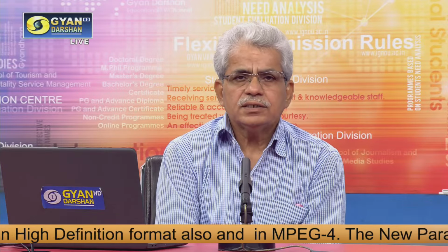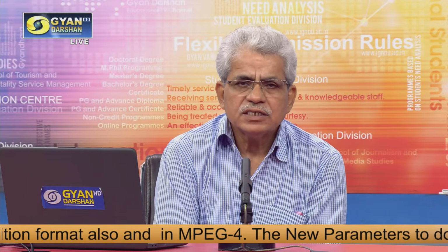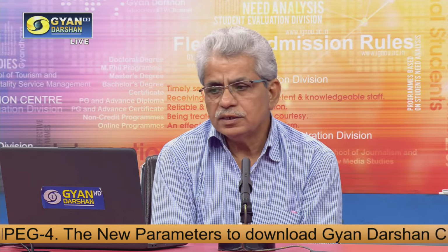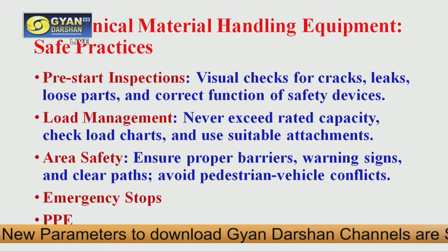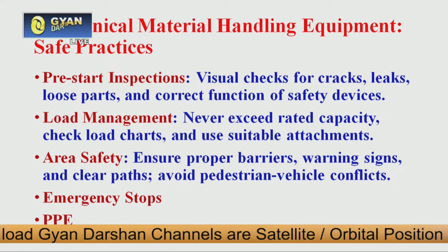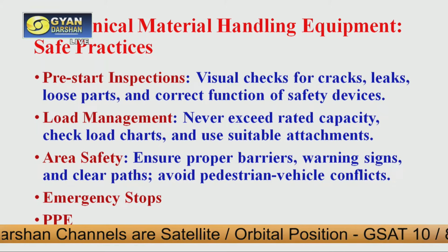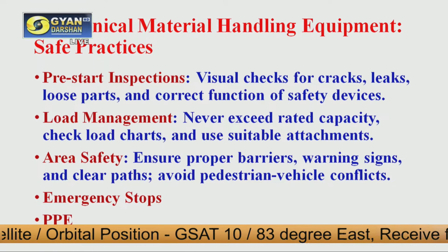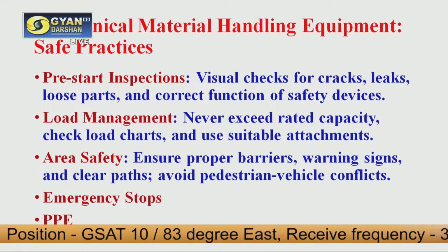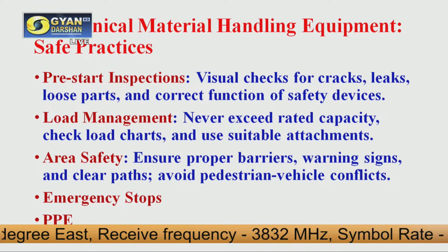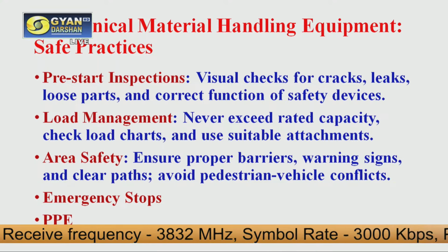Now let us talk about what are the safe practices while dealing with mechanical material handling equipments. What we should do to make our operations safe. So first one is pre-start inspection. Pre-start inspection means inspect your tools or machineries before starting the work.